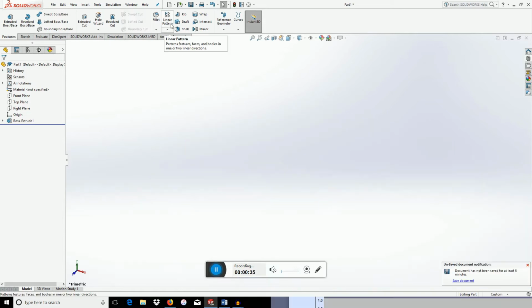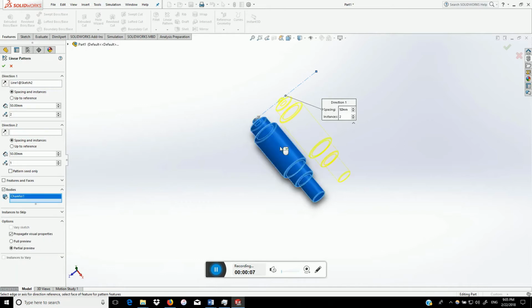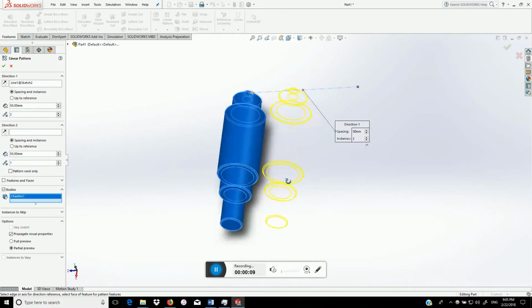If you want to make a toothed belt, you can make one of the teeth or gaps of the belt and just repeat it as a pattern. Just for reference, if you want to pattern in a straight line or flat grid, you can use the linear pattern. Just choose the directions you want to repeat it on, similar to the sketch pattern function.